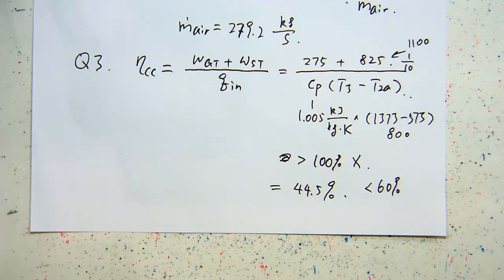And this is the primary reason, because this is driving the whole thing. And for the steam side, the steam turbine, we said in reality you can reach 620 or at least 600 degrees C, and we didn't reach that value. So these two temperatures, which directly control the efficiency, are not being used. We didn't use the maximum value there. So that directly controls the overall efficiency.